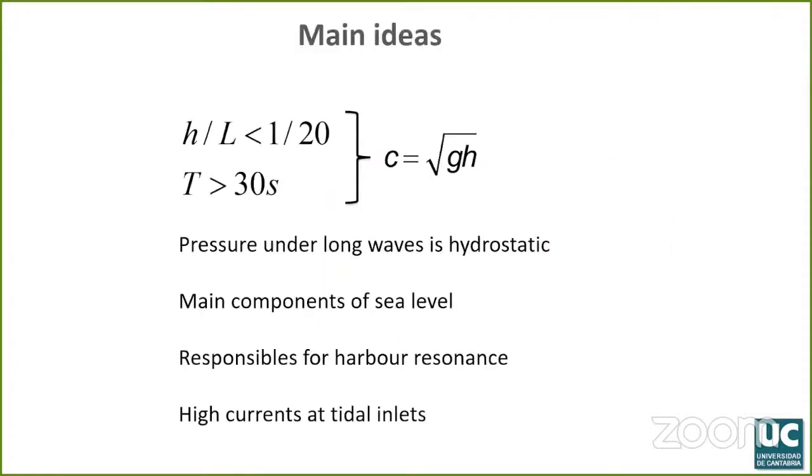To sum up, here are just some ideas to keep in mind. Long waves are shallow water waves with long periods and lengths. The long wave hypothesis is that pressure under long waves is hydrostatic. They are the main components of sea level. They are responsible for harbor resonance, and they can induce high currents.